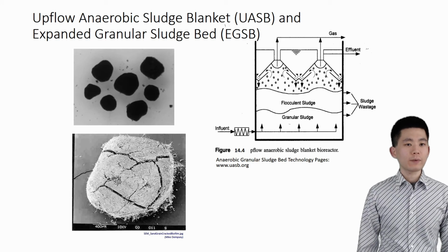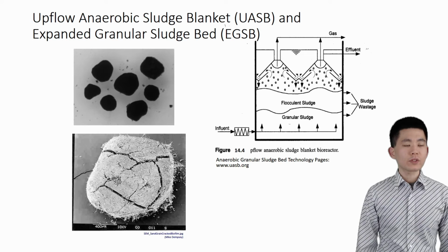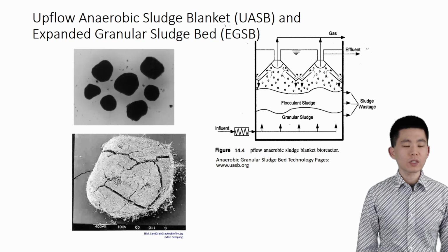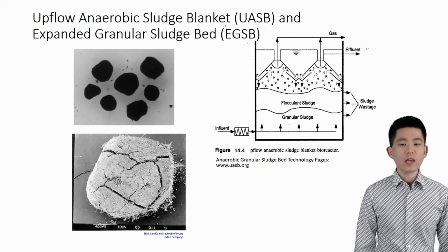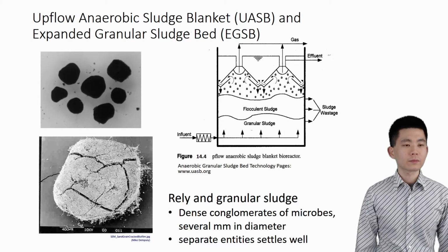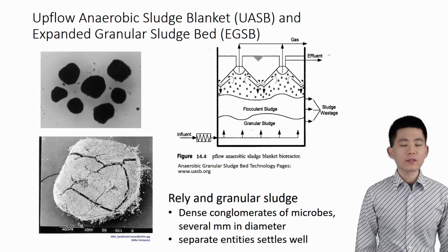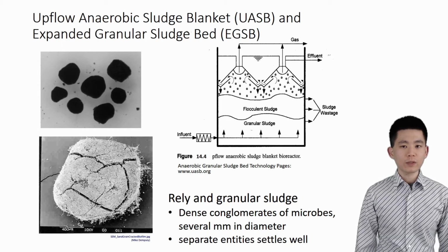As we have covered in Topic 2, upflow anaerobic sludge blanket and expanded granular sludge bed utilize fluidized granular sludge to achieve SRT-HRT separation and high biomass concentration. The upflow as well as the gas bubbles generated suspend the biomass and provide mixing. Healthy granules are millimeters in diameter and result in a high VSS of 20 to 30 grams per liter in the reactor. A short HRT of 0.2 to 2 days is maintained, which means a very small reactor footprint.